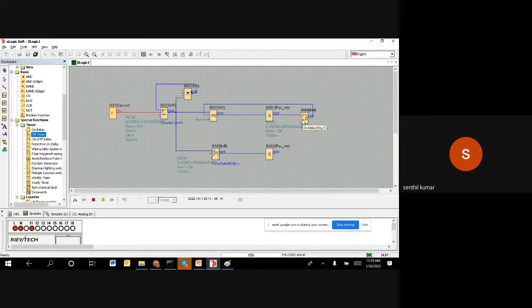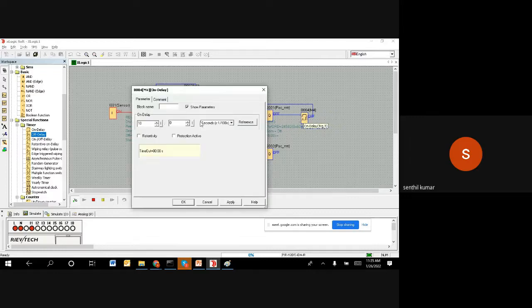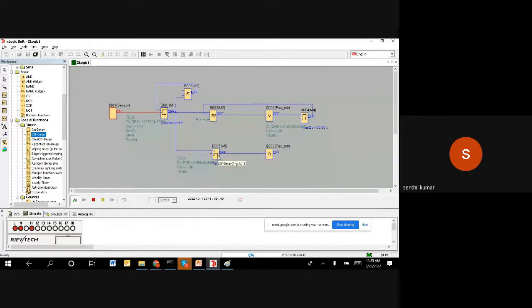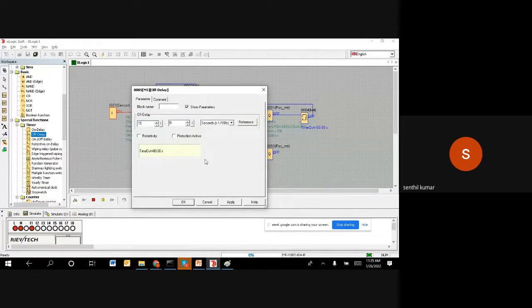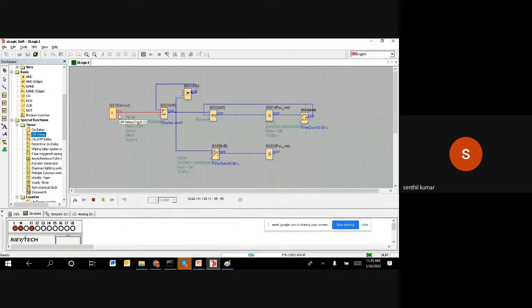Let us try again once more. Maybe we can increase the time to 15 seconds just to visualize better. Go for 15 seconds. So now I am going to make again 5 productions. See, now immediately the count has gone to 0 because it did an automatic reset after five counts. So we are going to make again count number 1, count number 2, count number 3, count number 4. If we make the next count, the motor will start at the fifth count. So it made it 0.